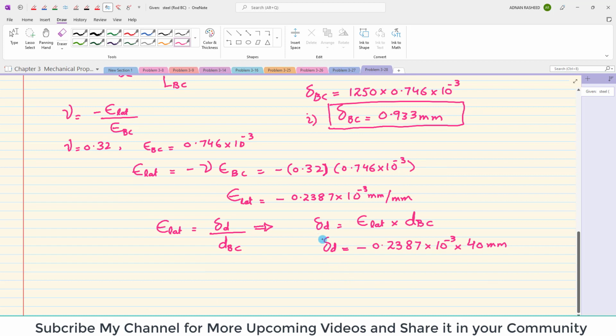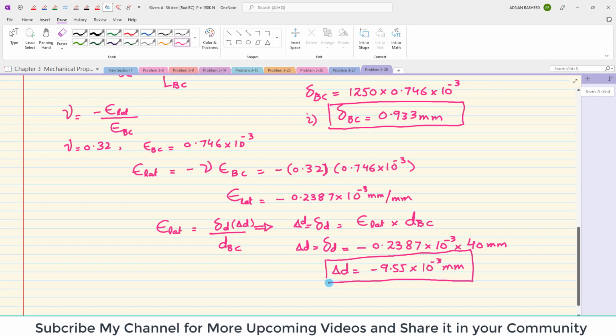We can also write delta D is equal to change in diameter, because otherwise it will confuse. So when you multiply it, change in diameter comes out to be minus 9.55 into 10 raised to power minus 3 millimeter. This means that the diameter of rod BC is decreasing, and the change in diameter is minus 9.55 into 10 raised to power minus 3 millimeter. So this is the answer of our second portion.